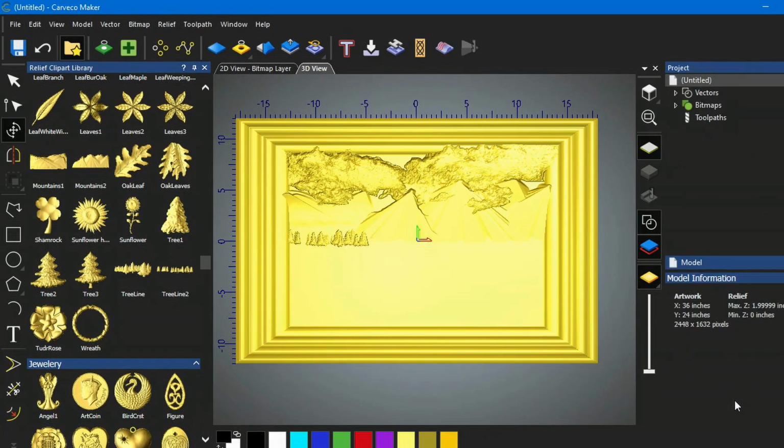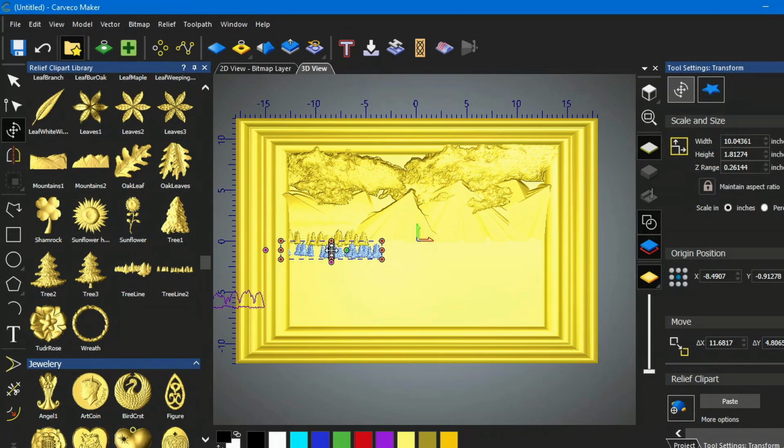Okay, paste it down. So we're going to catch hold of the same group and put them here. So it covers up some of the spaces, but we're going to make this slightly deeper. So we're going to go 0.3, because as you're working forward, overlapping the ones that you've already put there, you need to make them slightly larger.